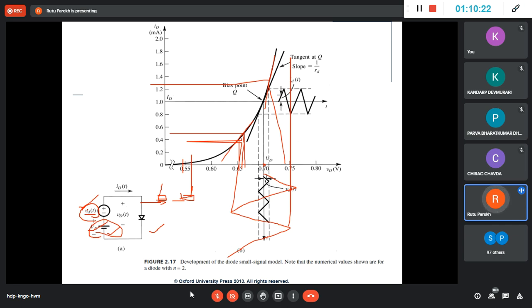If you take a broader range, your current will not follow, and this current which is flowing through this stage will again develop a voltage if you want the output as a voltage. So our input voltage and output voltage should be linearly related, right? They should be linear. So if the range is large, it will not give a linear relationship.